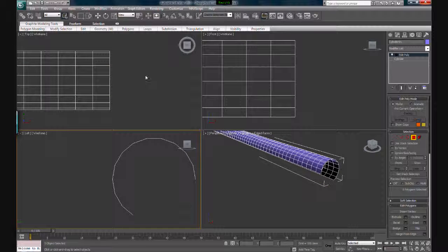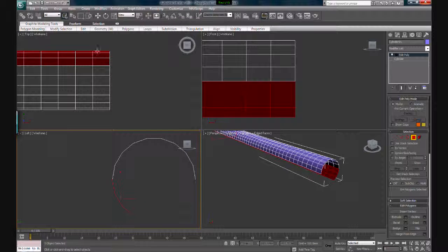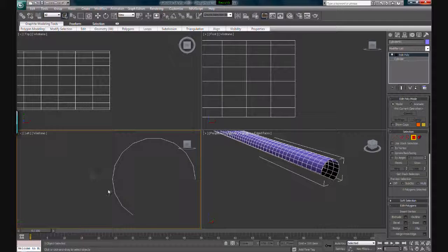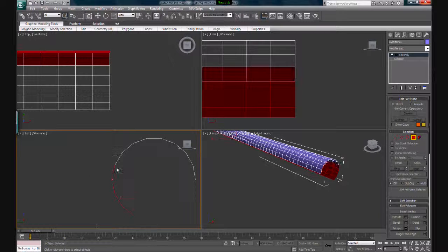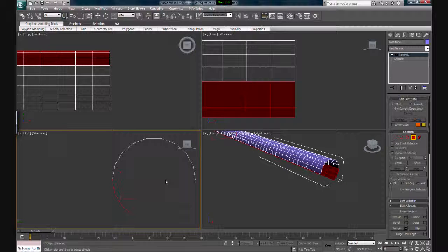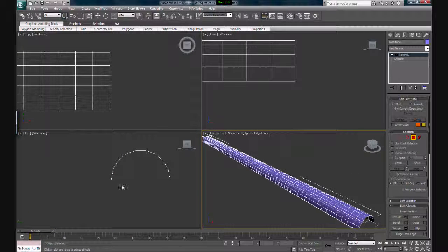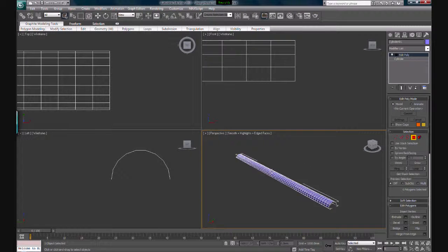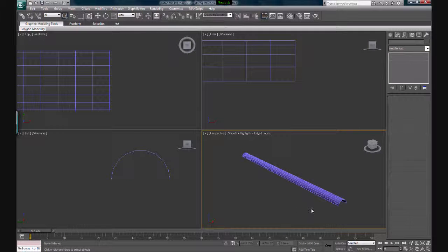Alright, okay, just for the record, there's an option here, this one here. It works like AutoCAD, where if you click on this, it will select anything that the cursor touches or the marquee touches. If you click it again, it will only select those within the region, you see. So you can choose whichever options you want to have. So I'm going to delete the rest. Okay, so now I have this half cylinder tunnel, and so okay, we're done. We have the basic form.